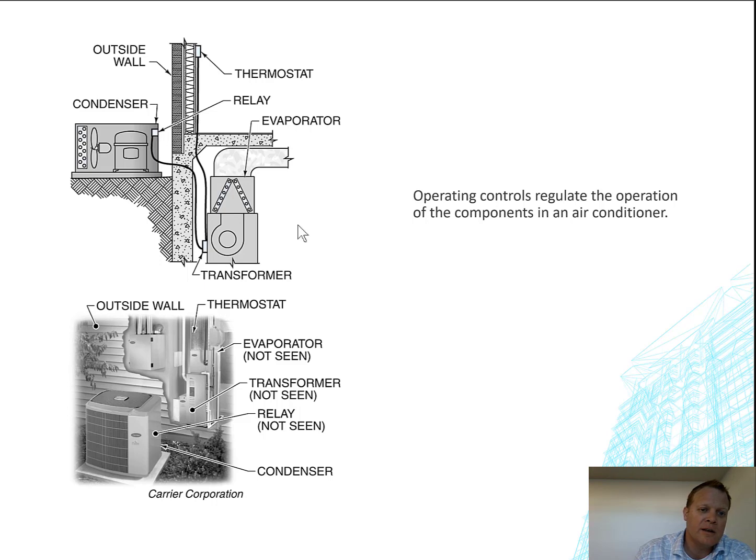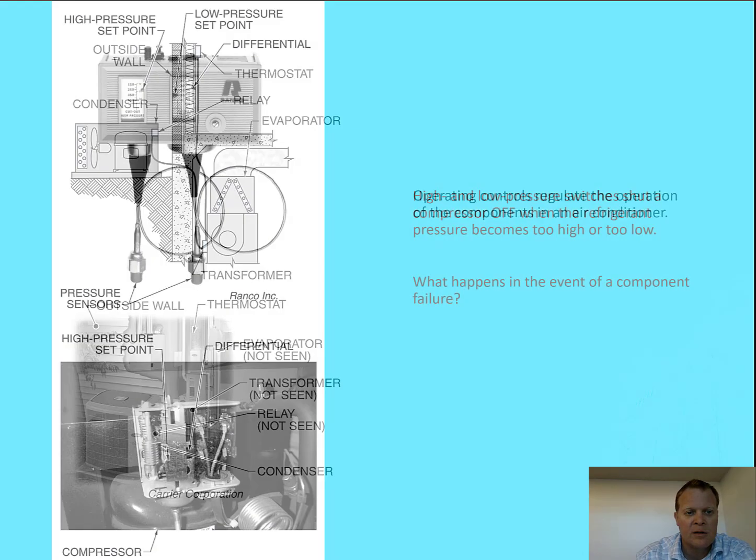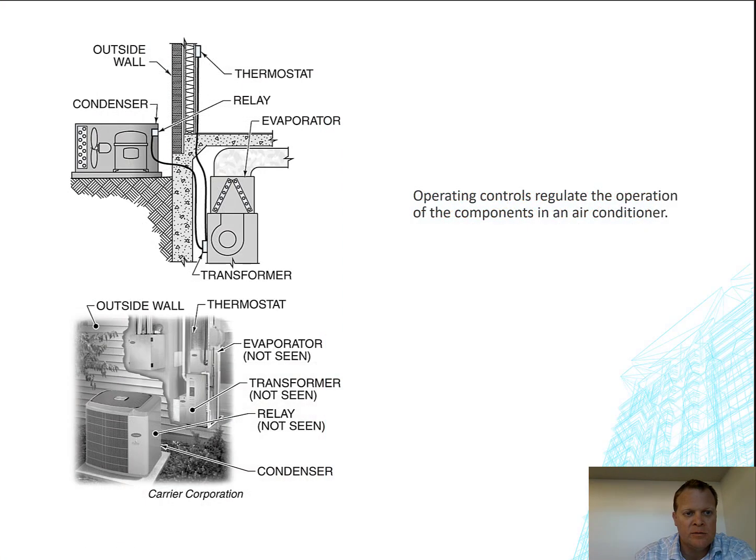Let's talk a little bit about our relay. Do we have, oh, we do have the thermostat here. So we need some coordination here between where are we going to put the thermostat, how are we going to route the low voltage wire, where are we going to land the power at for both of these. Don't we need a disconnect as well? Let's see if I have a slide for that. I don't think I do.